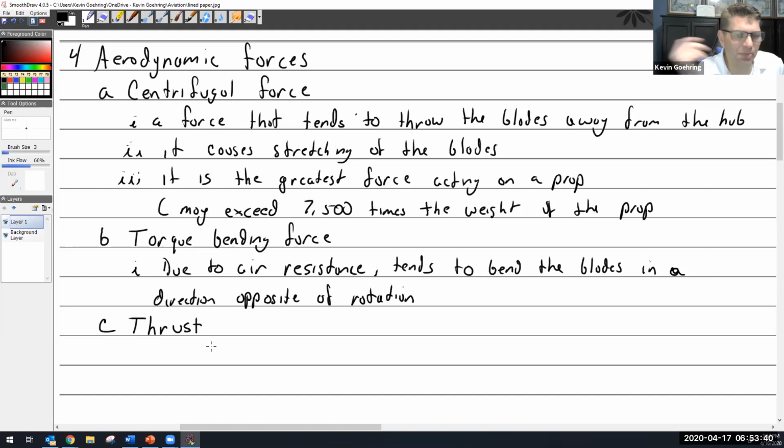What they do to these props is they bring them in and they actually take off a surface layer of aluminum. They make the whole thing thinner. The prop develops stresses in it, and these stresses rise to the surface. By taking off a layer of the aluminum, you remove the stress out of the blade so it doesn't crack, which I think is just crazy, but that's what they tell me.